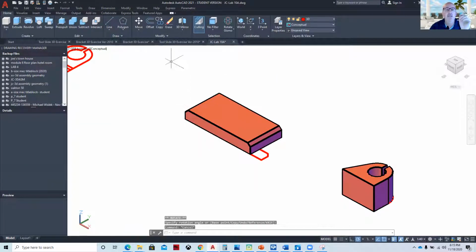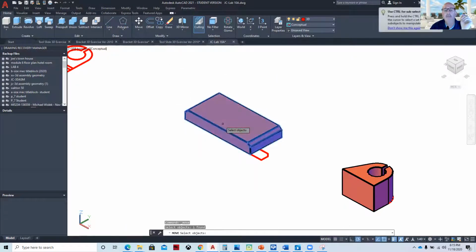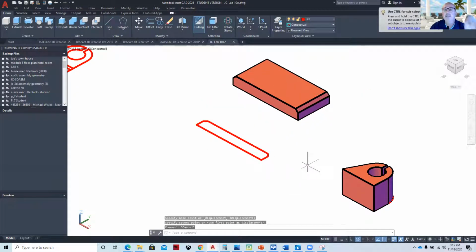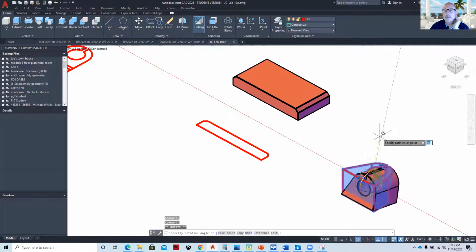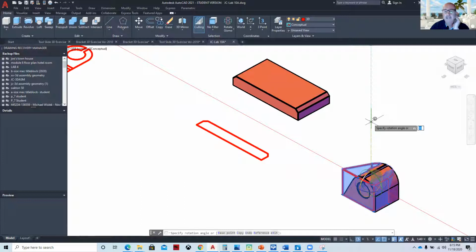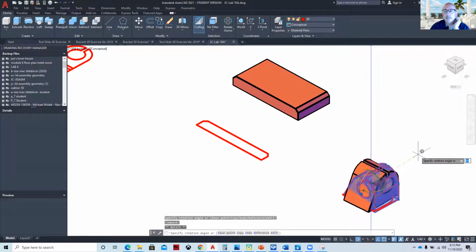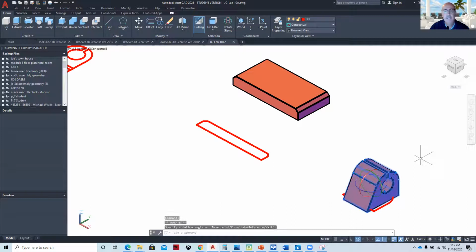And then I'll hit escape, move the part off the ghost image, hit escape, and then do the same thing with the rotate gizmo. Click on the part, rotate it until it stands up straight. Like that. You can see I've got a tracking line from my polar, and then move it again until we track. Hit escape.